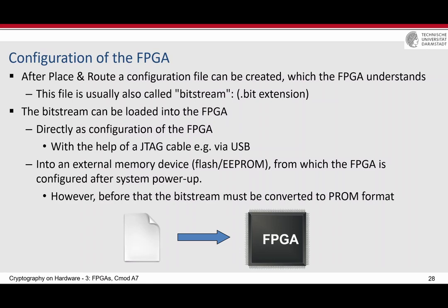If there is only a JTAG port here, then you need a programmer. Then you need a program connected to the USB, and the programmer to the FPGA board, to configure the FPGA.